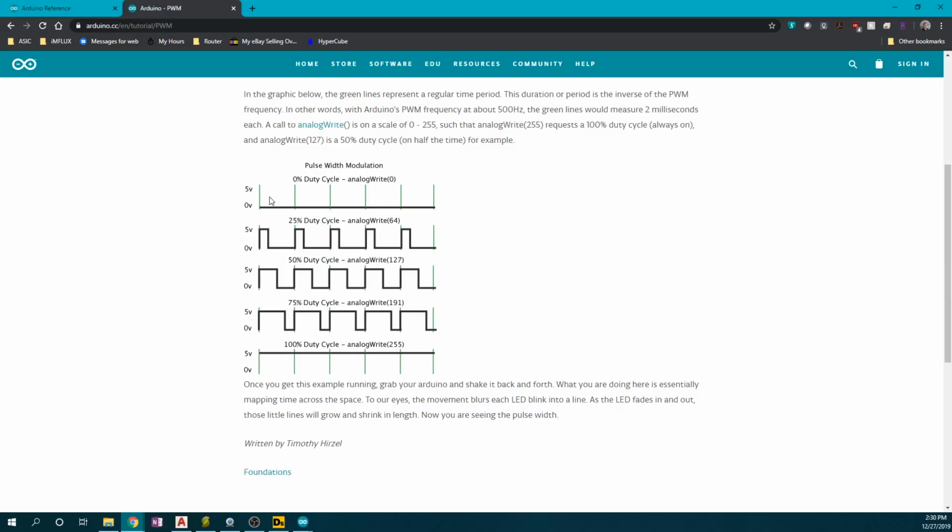It'll end up appearing to be a voltage, but the Arduino UNO does not actually output a voltage of 0 to 5 volts. It outputs a pulse width, and most devices that you can buy online will interpret that as an average voltage, but not all of them. So you can get into trouble if you don't filter it out sometimes. But for some simple projects, this works fine for the pulse width.